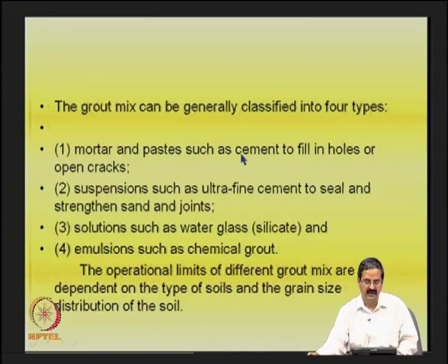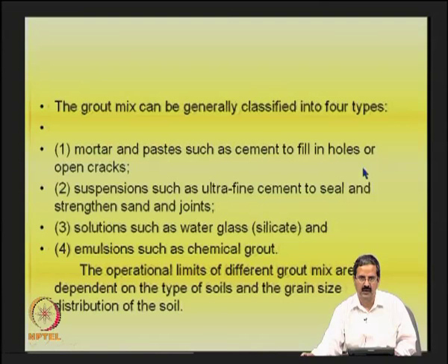To understand further, we can classify the grout mixes into 4 groups: mortar and paste, such as cement, to fill the holes or the open cracks; suspensions, such as ultrafine cement, to seal and strengthen sand and joints; solutions, such as water glass; and emulsions, such as chemical grout.